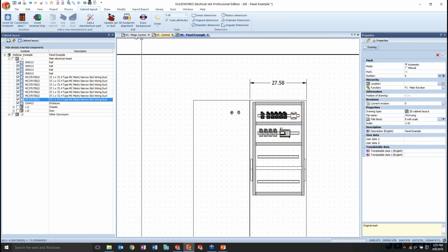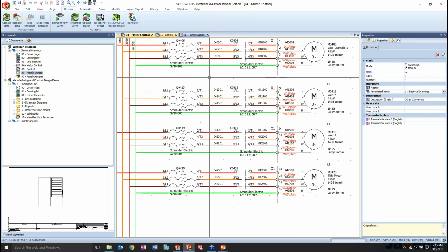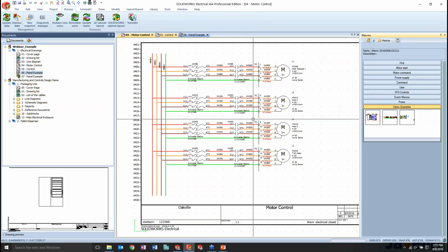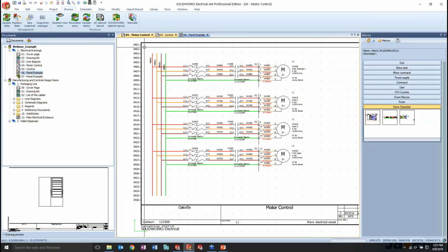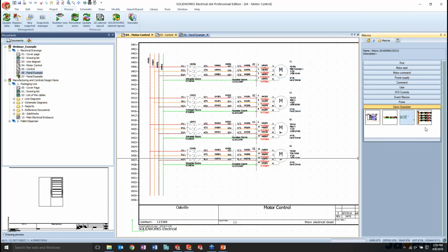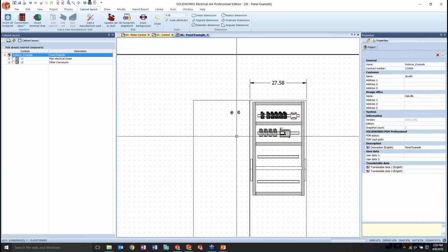And as you're doing all this, of course, we did our schematic, we did our wire numbering, we added some part numbers in the macro itself. Just as an example on how you save this macro, so if you do this all the time, you can select this, drag and drop it, and click OK. And now that macro is available. So if you wanted to add more parts, I just wanted to make sure that you guys understand how the macros are done. So it's a very easy way to use circuits that you have designed before, and from there you can start designing your panel fairly quickly.